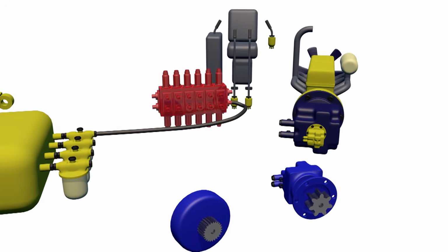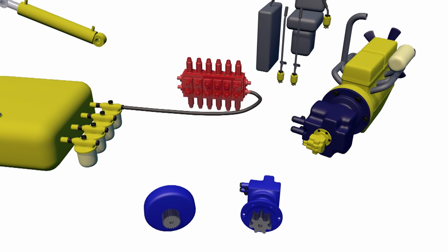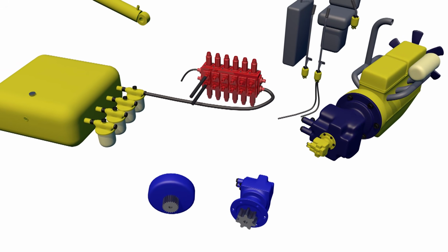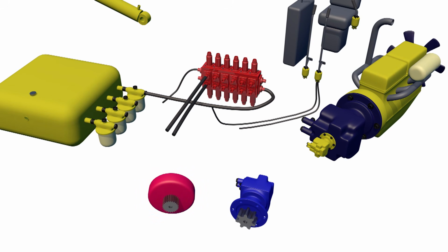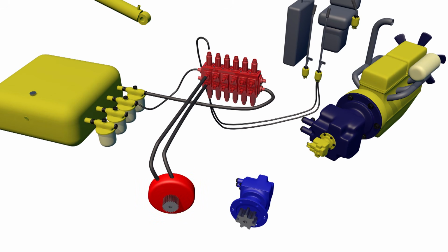Hydraulic motors are used to move the excavator. Each track is equipped with a hydraulic motor. In our video, for example, one hydraulic motor is shown. The operating principle is the same as that of the swing hydraulic motor. The excavator is set in motion by moving the front arms forward and backward. Each arm operates independently of the others. This allows for turning while moving. It is even possible to drive the tracks in opposite directions to turn in place.